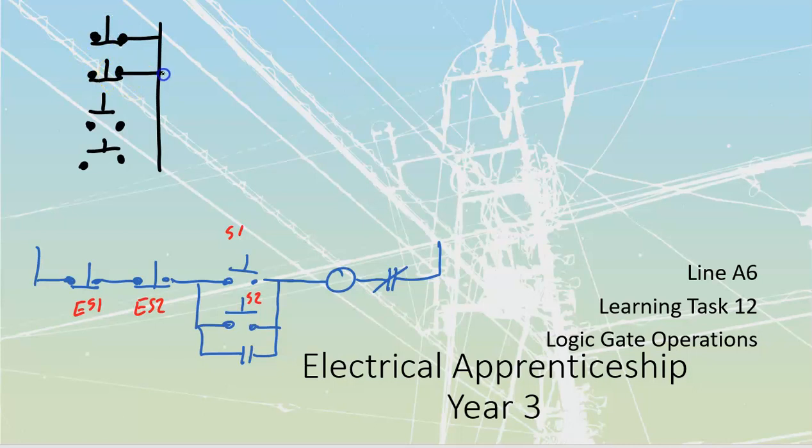These are all going to come into my PLC. We're just going to draw this line here just to separate where the field wiring is going to my actual component. This is the beauty of programmable logic controls and digital controls in general: instead of having all that interconnection of lines going back and forth, all that I need to do is take a plus 5 volts in this case, run that plus 5 volts out, and then I'm able to just grab a direct plus 5 volts off into every single component over here. It's fantastic, quite honestly, because my wiring is super simple.